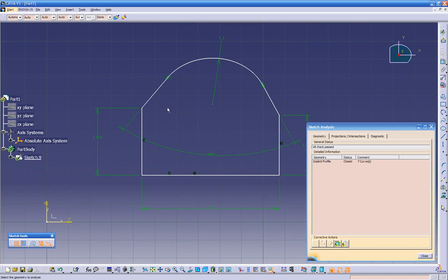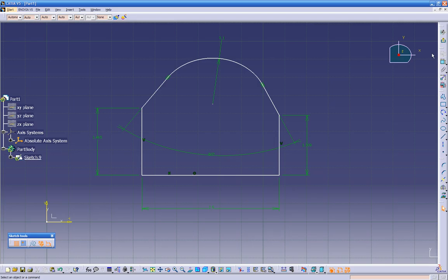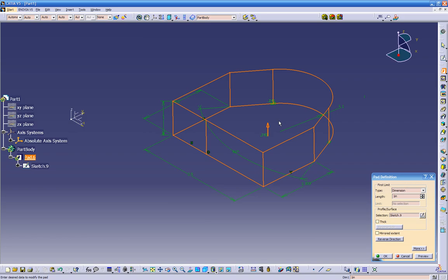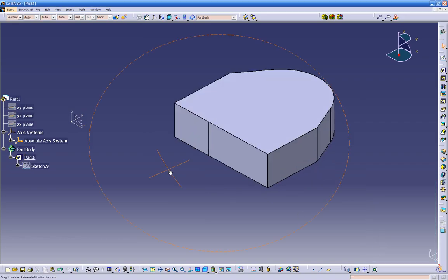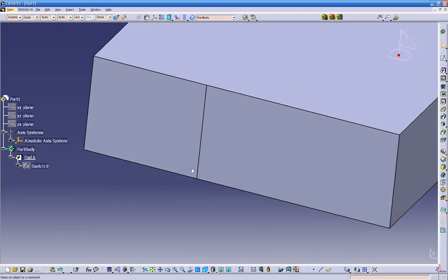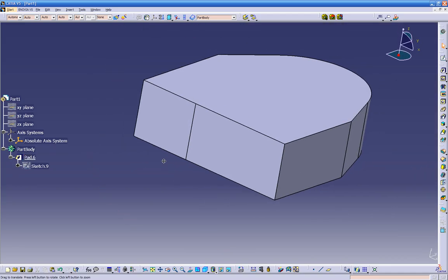I like it a lot because sometimes I have complicated contours and I don't know where the part is broken. You can see over here a whole bunch of broken contours, and I just click on it and close it. Click and close. Okay, so if we get out of the sketch and try to do a pad, click OK. See, we can have the pad, but at the same time we have this line in the pad. This line shows that our sketch was broken over here, which doesn't affect our pad at all. It has nothing to do with the pad.